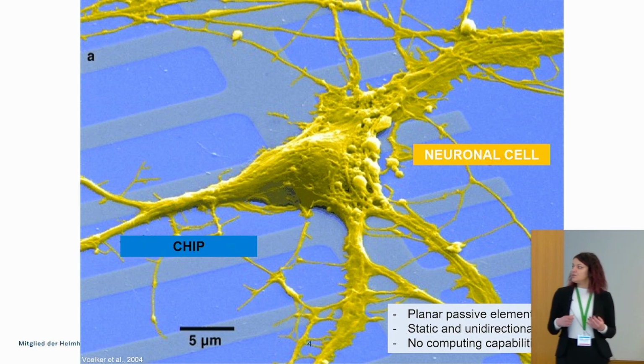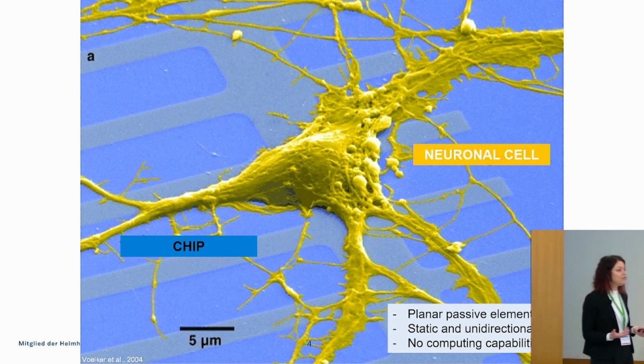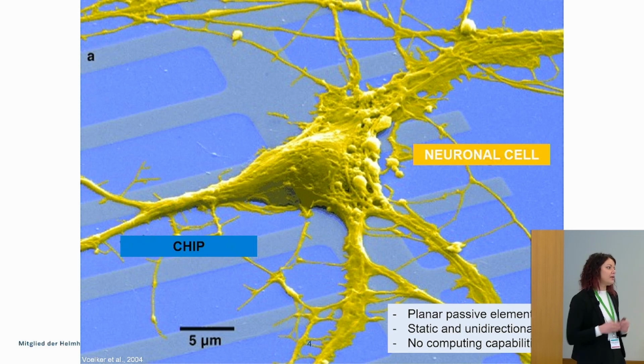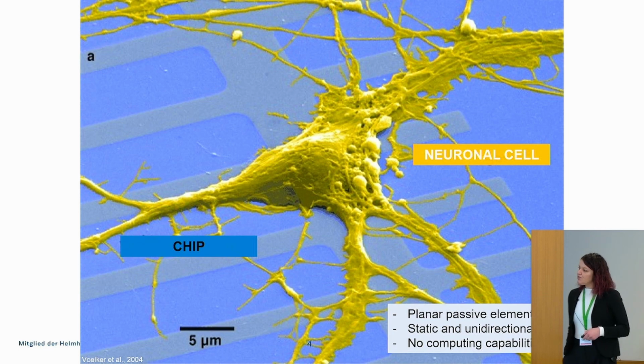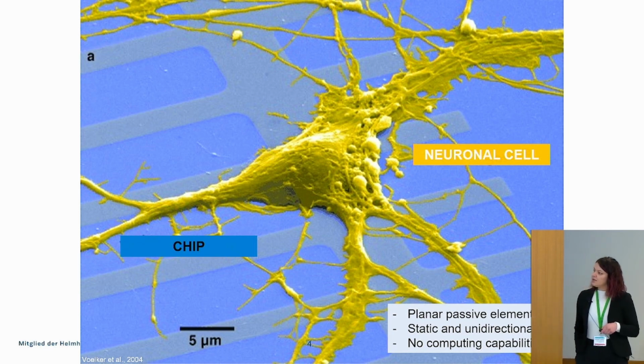So this is working in depletion mode, meaning that when the bias at the gate is 0, the transistor is on, and we can modulate the channel current by applying a bias, decreasing the conductivity, so dedoping the polymer at the channel, when we modulate the bias as an input. And so what is also very important here is that, as I said, when it's 0 at the gate, we have a current flowing in the channel.